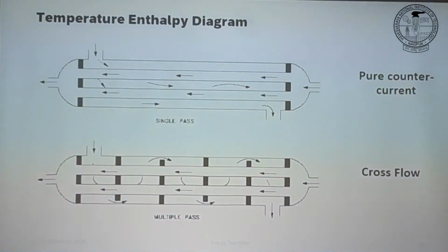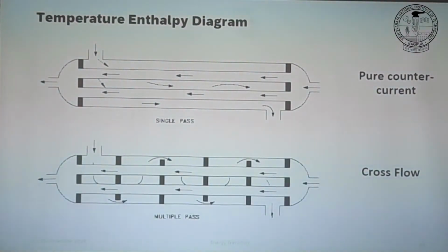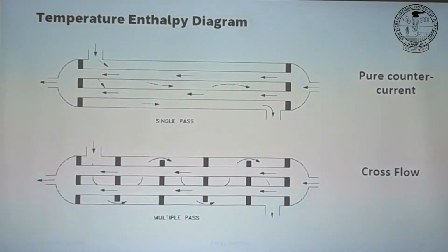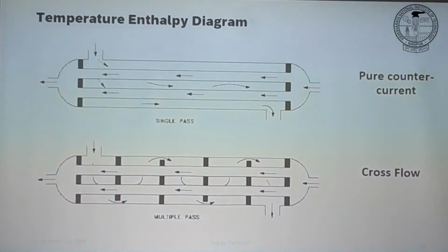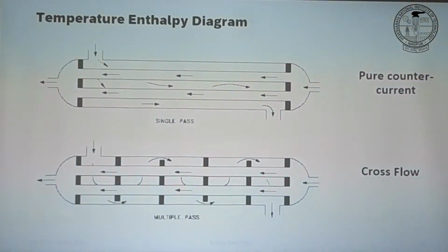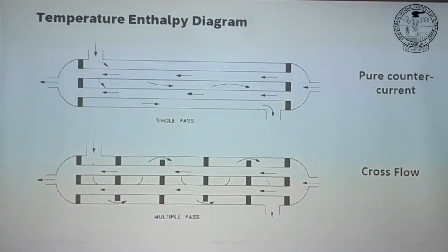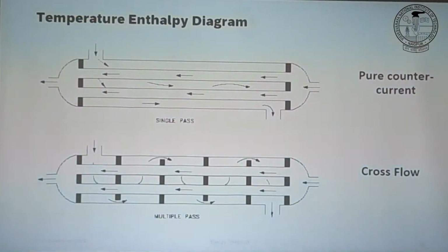Yeah. The scaling or fouling tendency fluids go on the tube side. Even the cost of the tubes used to be relatively very low, as compared to the shell, right? So if you need to replace the particular element because of the fouling and those problems, in this case the tube, replacing tubes will always be beneficial and economical, right? Because if something happens, you can drop that tube or the entire tubes and put in new tubes, because those are very cheap. Right. So that is also another way.